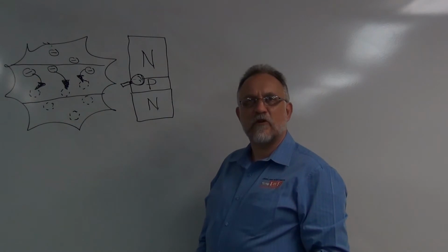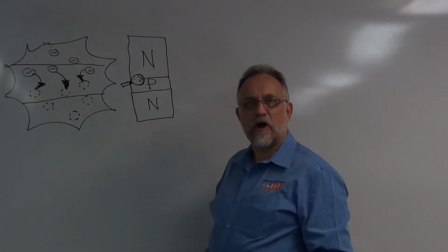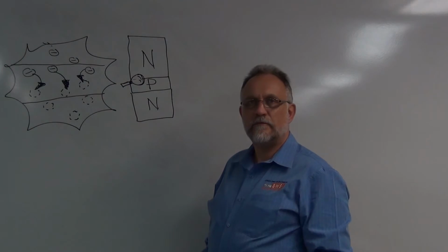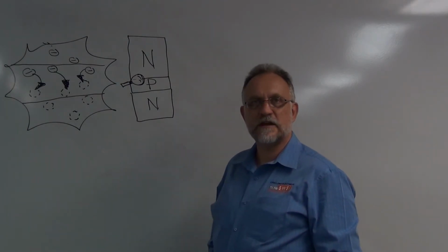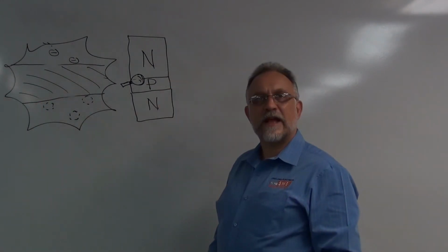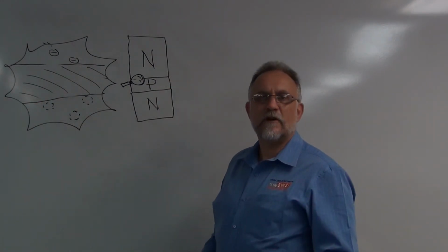Once the spare electrons fill those electron holes, what's left in the middle? Just perfect crystal. Non-conductive, perfect semiconductor crystal. It creates a layer which is depleted of all charge carriers. The term charge carrier is a general term that can describe either the free electrons, which of course are able to migrate through the material, or the electron holes, which can attract an electron from another atom and similarly cause the migration of electrons.